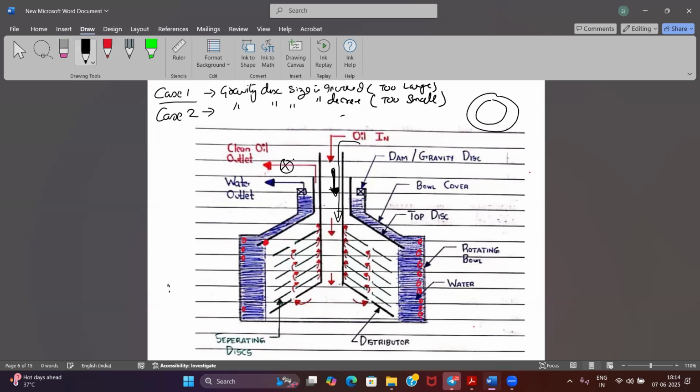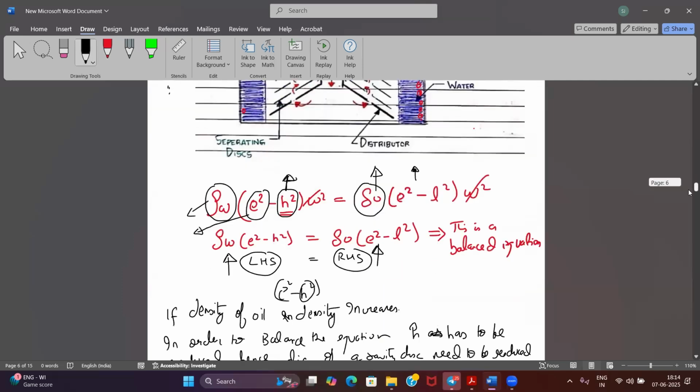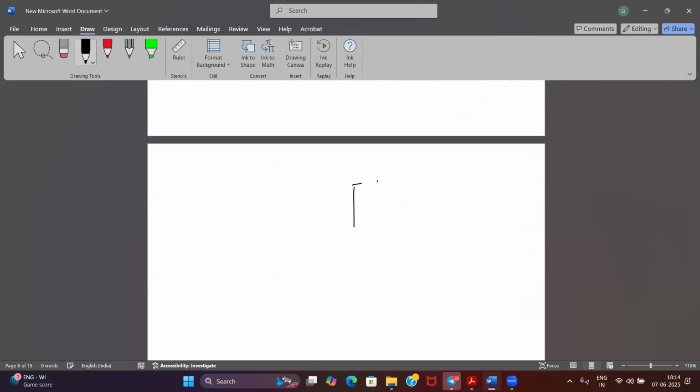The back pressure valve will create a minimum back pressure onto the system so that fuel gets enough time to remove sludge and water. Back pressure valve is what I'm talking about; the bypass valve is different. Now when fuel comes, you all might have done only auto purifiers.